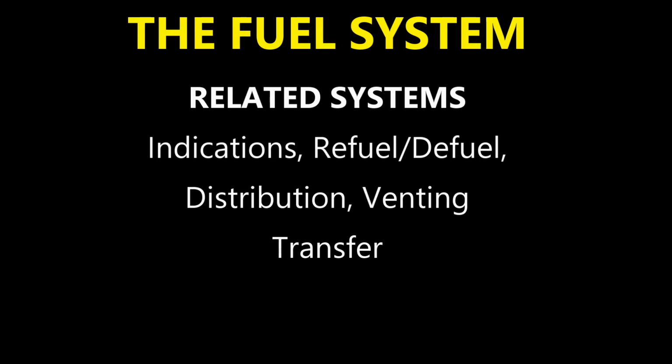Now there's a collector cell. That one is located between 2 ribs, and also the front and rear spars and top and bottom skins. You're going to have the collector cells, and there are also clack valves. Those are in the bottom of a certain rib number. Your sequence valve I mentioned before. Those are on each wing pumps canister.